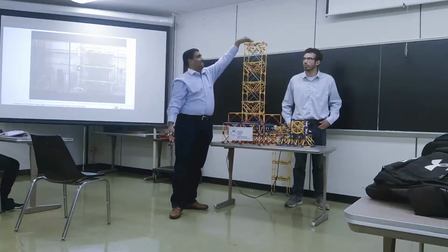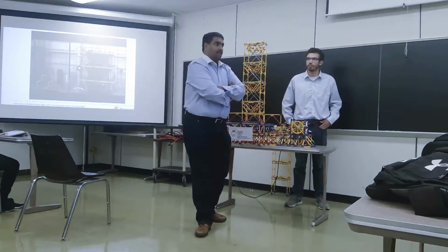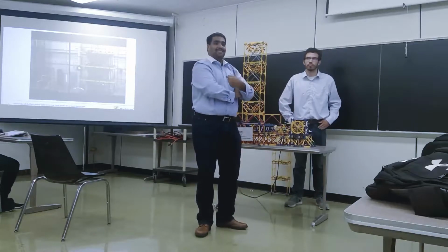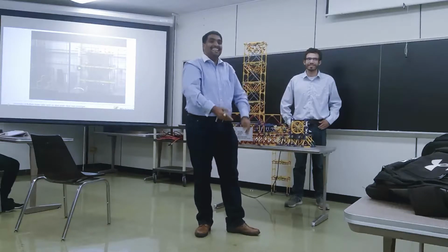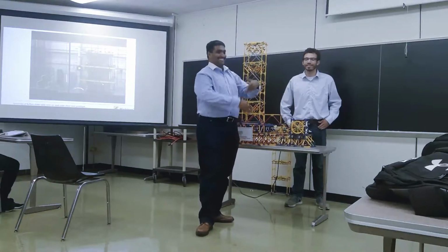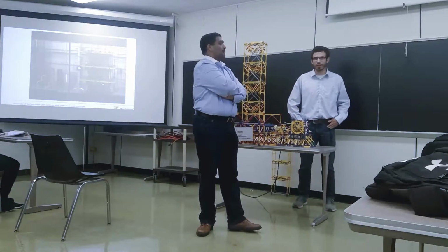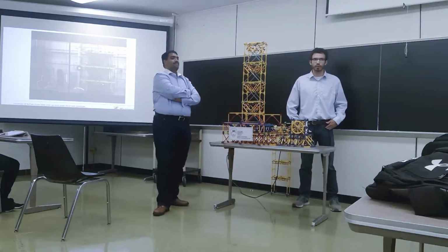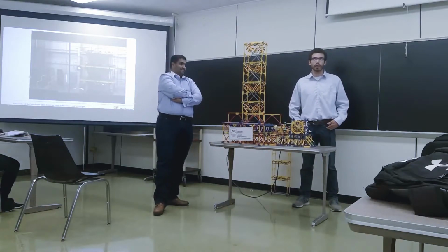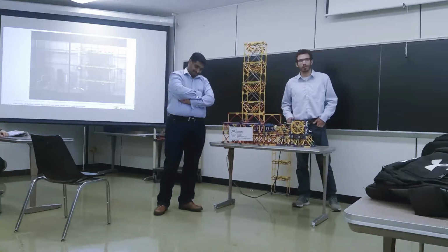Especially for buildings, we cannot move it up and down. That's an assumption. That's a good assumption. Having said that, all my research is trying to find the vibrations in Z direction. So in that case, we cannot assume Z is 0. Yes, that's a good point. There is vertical vibration in earthquakes. We do have records of that, but it's not as significant as the lateral forces. Generally speaking, you design buildings to resist vertical loads. So they should be fine if you have a little bit of vertical vibration.